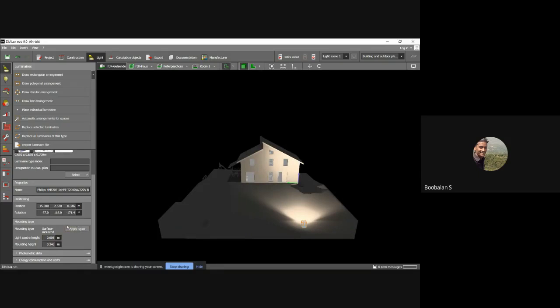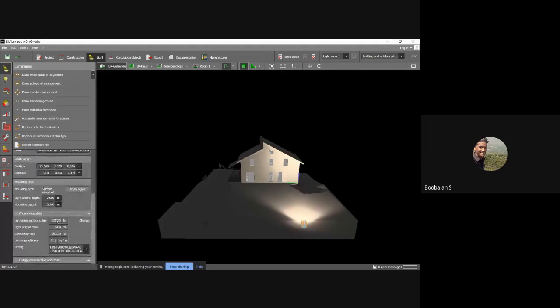You can change that entire lighting system and photometric data. You can change your lighting system lumens. You can change 10,000, 1 lakh, around 1 lakh 38,000 lumens will be here, because a focusing light is going to consume much more electrical energy. Let's see, this focus light alone is going to consume 2000 watts. Imagine 2000 watts, like a motor or power supply, it's consuming, because it's a focus light, right? So it has that much flux, 10,000 lumens, right? That's why the electricity will also be very high.